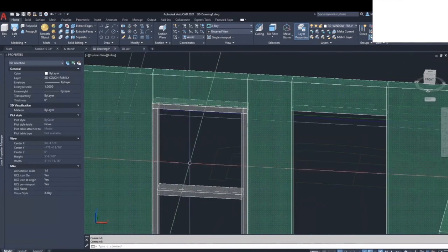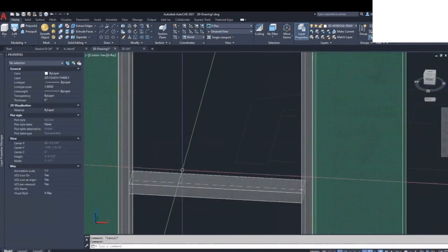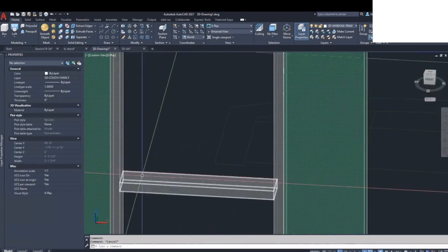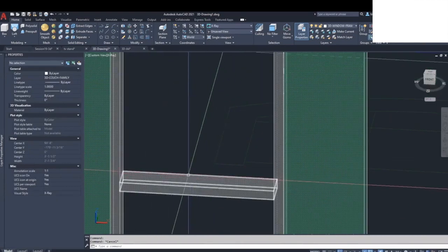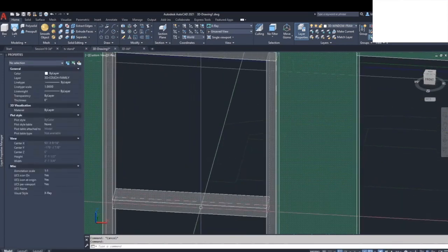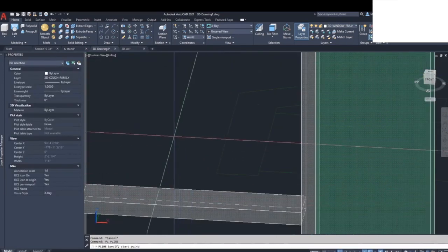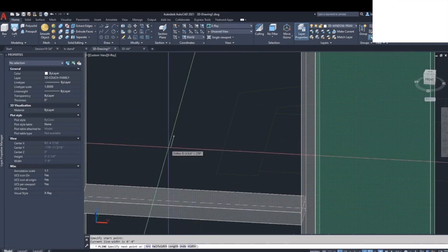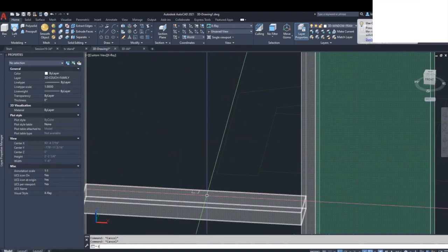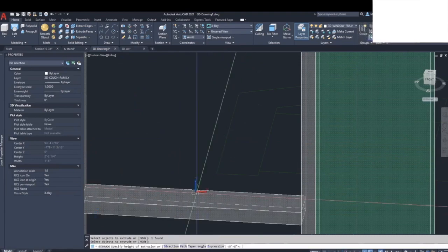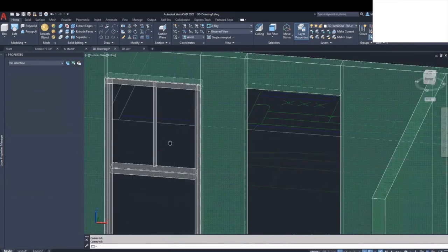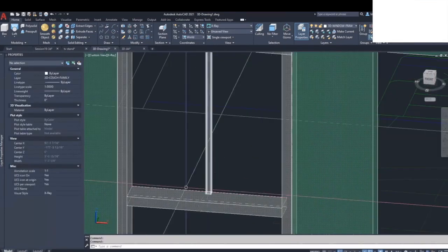I could put some more smaller mullions across this to make that look like an actual piece of an actual window sash, right? And again, for that, let's do it this way. Let's draw the profile of that. So let's say it's only about 1 inch by 1 inch by 1 inch by 1 inch, close. I'm going to move this to the center of this mullion and extrude this up to the height of this. Okay. So that's a mullion. That's a vertical mullion.